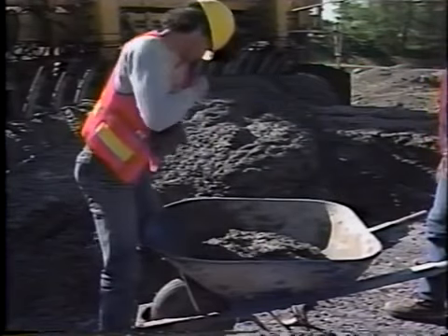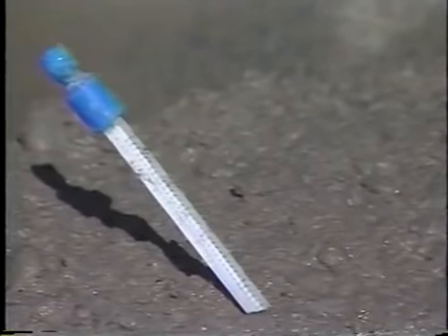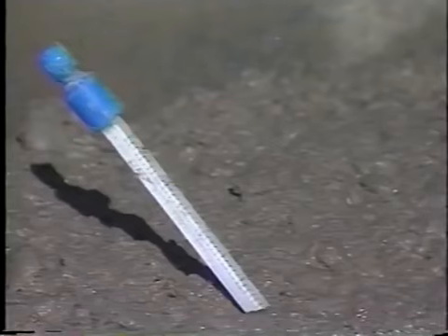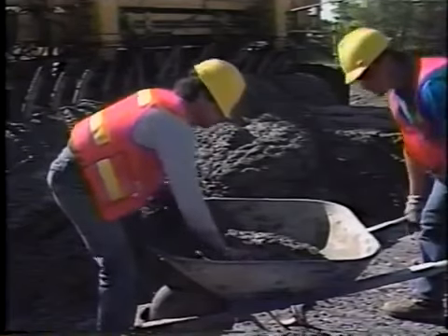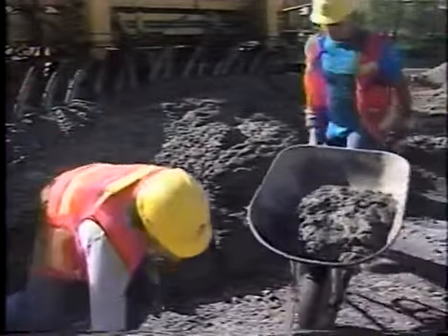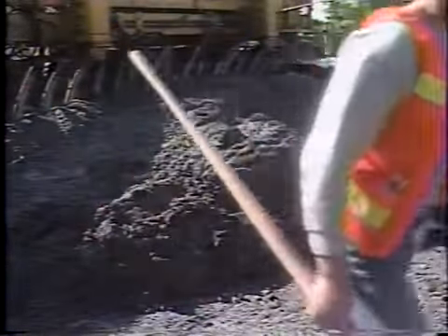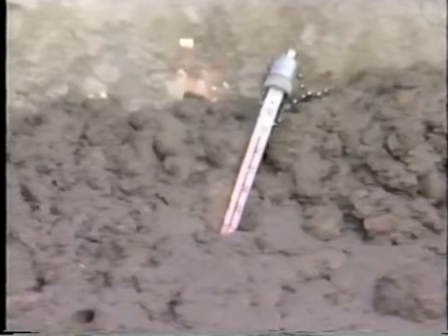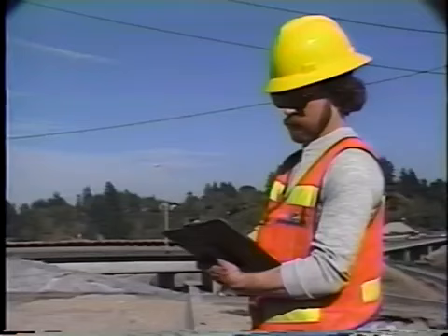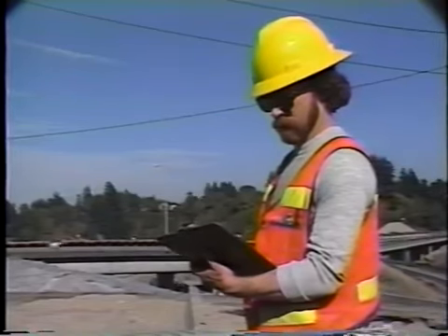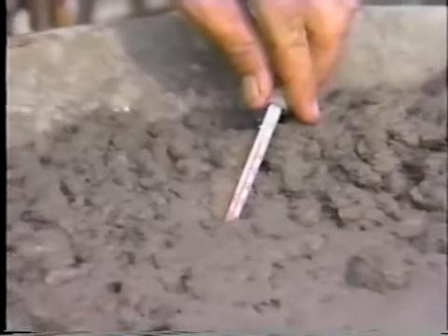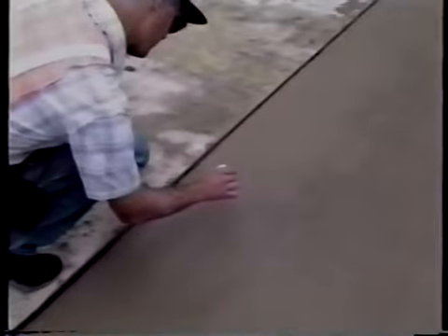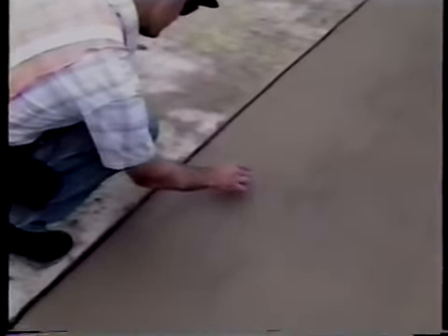The thermometer is inserted into the fresh sample so that the temperature sensing portion is submerged at least 3 inches. The concrete should be gently pressed around the thermometer so that the air temperature does not affect the reading. The thermometer is left in the concrete for 2 minutes or until the temperature stabilizes. Then the temperature is recorded. The measurement must be completed within 5 minutes after the sample is obtained. The temperature of in-place concrete is measured in the same way.